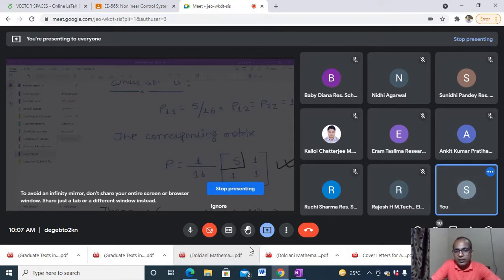What we have seen is that, at least for linear time invariant systems, and I will extend that in the next class to linear time varying systems also, I can construct a Lyapunov function using the theory of positive definiteness of matrices. After that, the Lyapunov equation comes into the picture. Under what situation do I get a unique solution, or a unique Lyapunov function? Unique Lyapunov function means I can create a unique P.